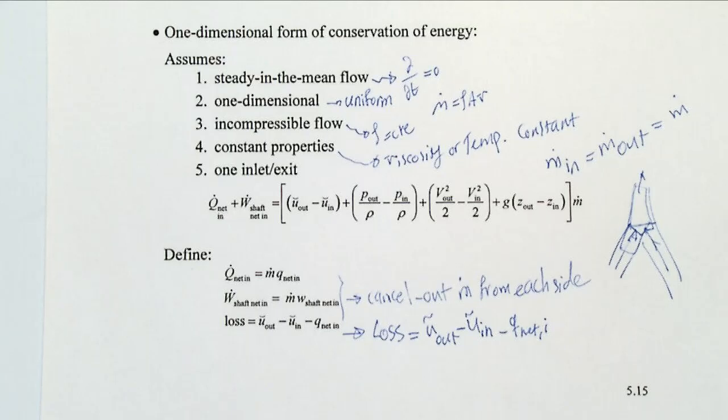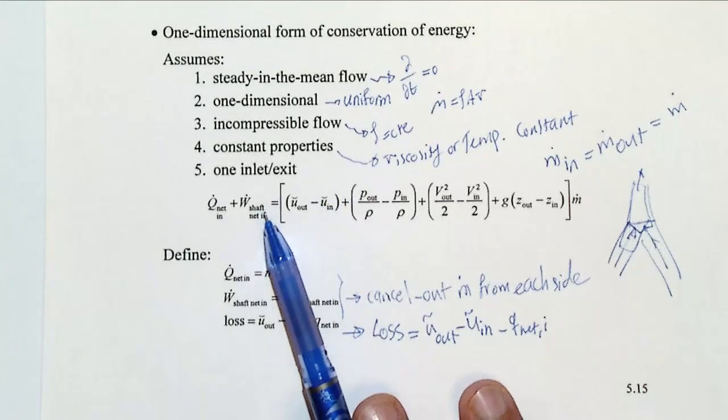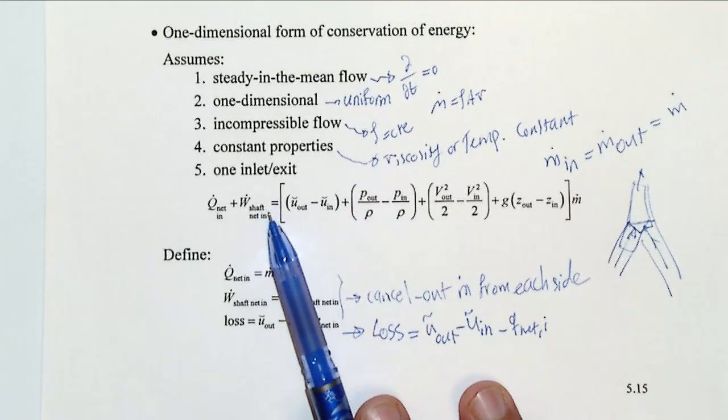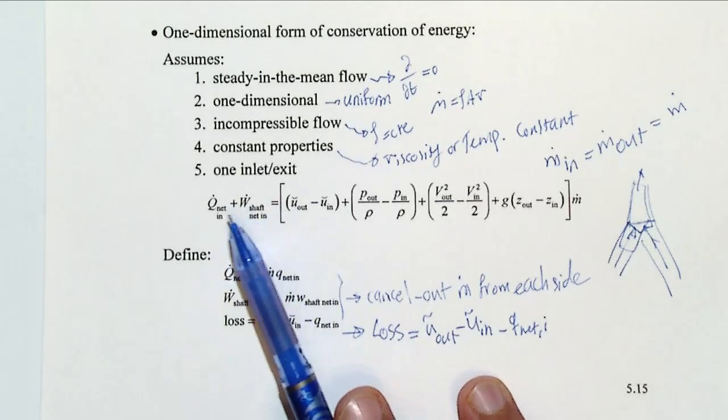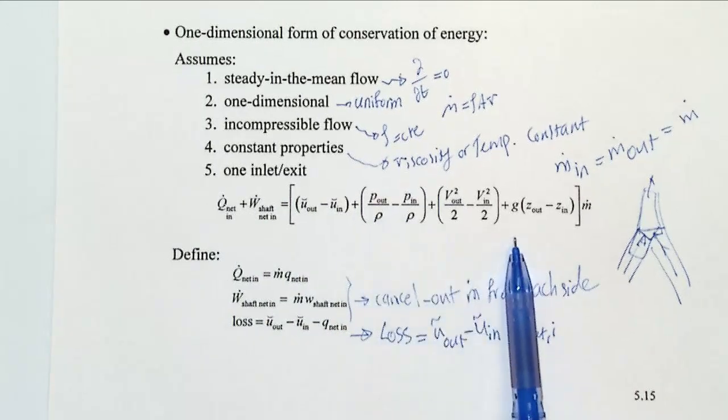You know that friction changes kinetic energy to heat, right? So inviscid flow means that Bernoulli assumes that you don't have that Q net, so U out and U in are going to be equal, and then it's going to be 0. If you don't have any work on the system or over the streamline, this is going to be 0, and since you don't have any loss, the Q net is also 0 because the flow is inviscid. Okay, then what will be left? The Bernoulli equation is valid.